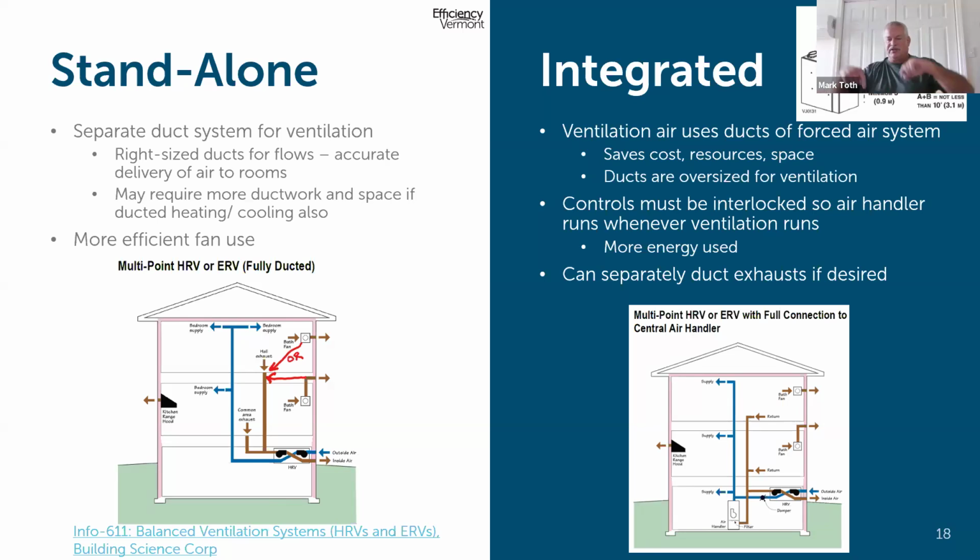So you're going to be moving fresh air into your system. As it comes into the system, it goes right into the blower, gets dispersed through the whole house at a very low speed. So you are now moving air through every room in the house because your heating system, your cooling system is obviously dispersing air through the entire house, where a lot of times with an ERV, HRV standalone duct system, you don't get everywhere. You have to pick and choose where you're putting and taking air from. But with the whole house ductwork system that's already there for your heating and cooling, you're pretty much going to cover the entire house with fresh air.